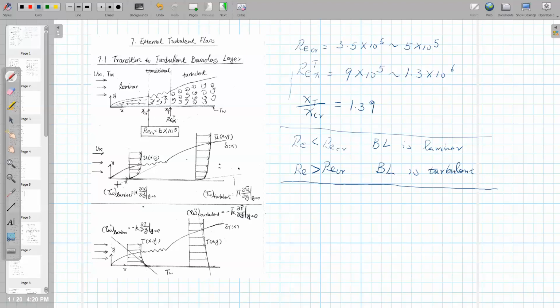Okay, so if you draw a slope of the u velocity in the y direction, this slope times mu will be tau w, the wall shear stress. So it will be equal to mu partial u partial y at y equal to 0.